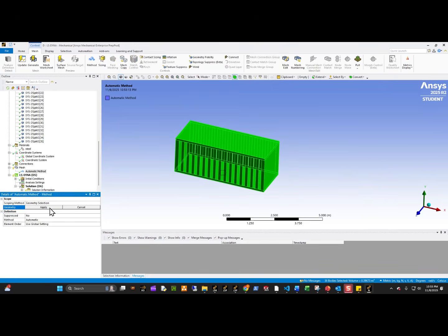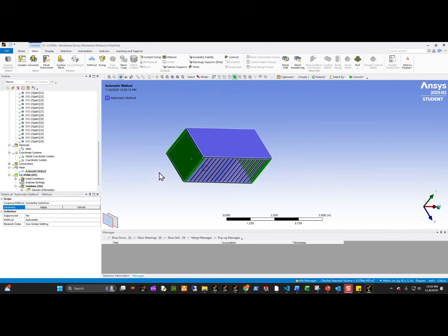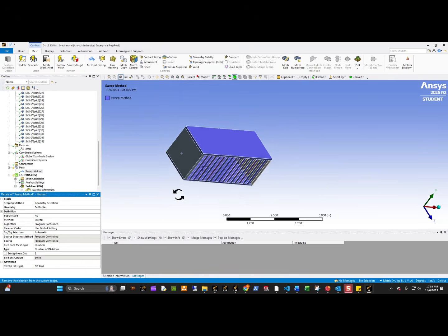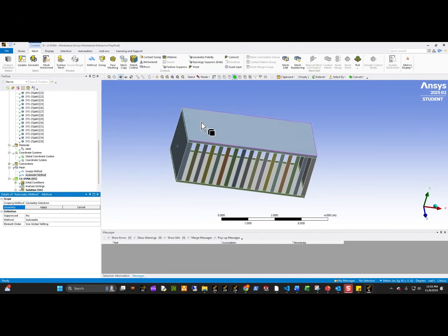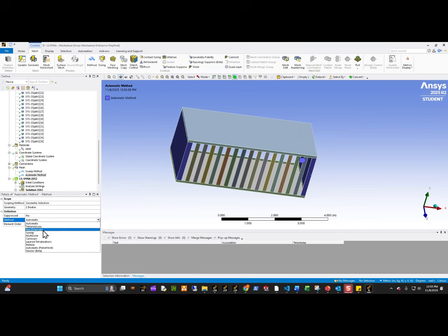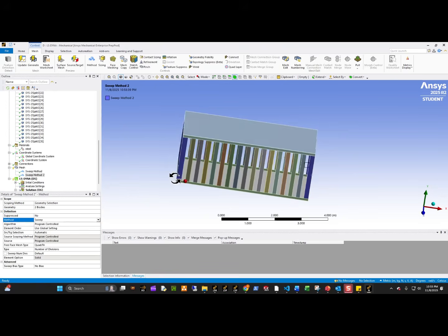Let's put there. That's all of the body, and then what I'm going to do here is deselect this one and this one. So the first sweep has only 3 element corner thickness for each of all of these bodies. For the other one, I'm just going to make them into a sweep, but I'm not going to define cross sections, so you can mesh properly with the right amount of elements.